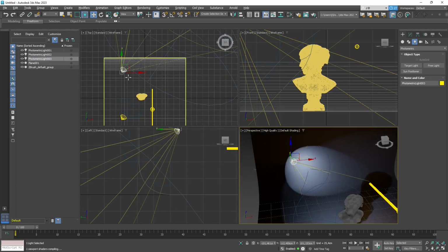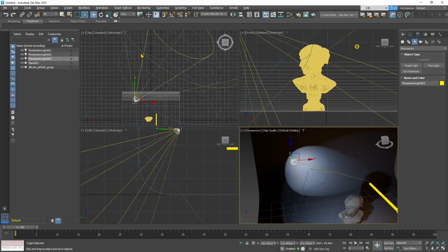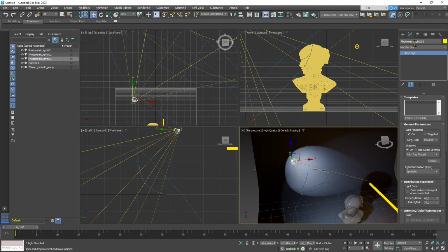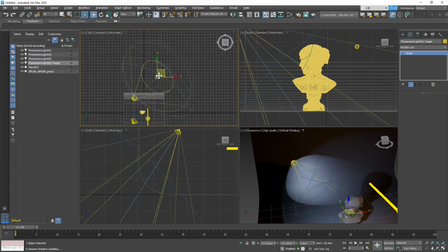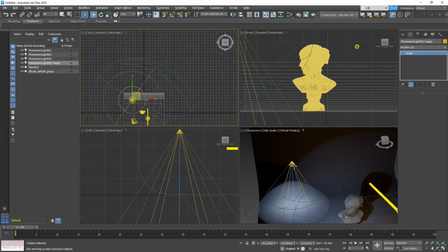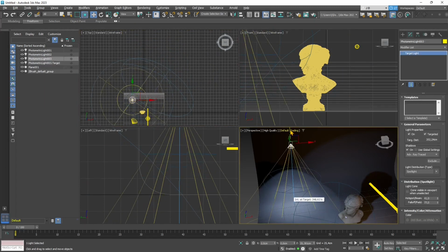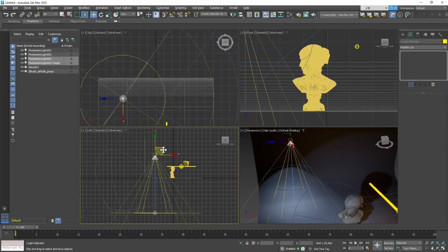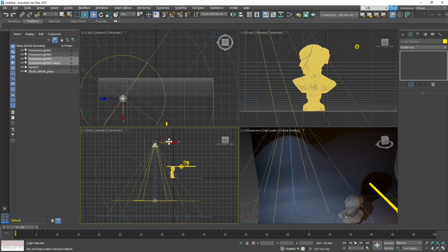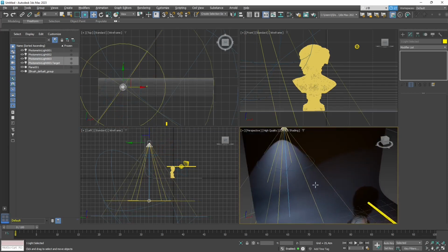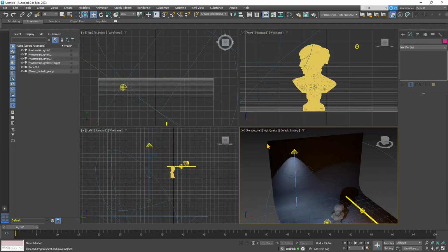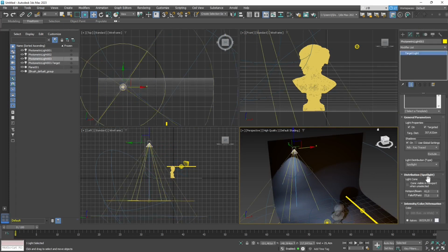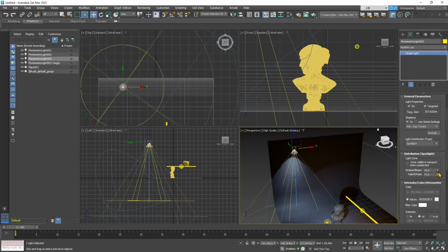So you can see here that this is a directional light, and if I want to actually see the cone of the spotlight, I just need to rotate it and place it with it. We can switch the target option on anytime, so you can add a target anytime, and we can direct our light using the target. And again, when you use directional lights such as spotlights, I think the target is going to be really helpful. So I select both, and now I can move them up a little bit and back near the wall, so we can see the actual cone. And we can see then the hot spot beam and the fall off a little bit better.